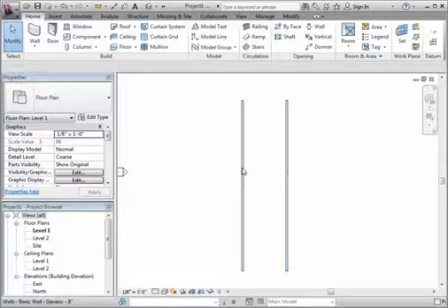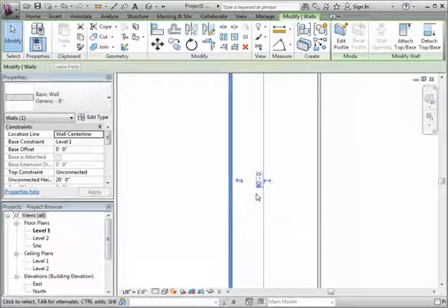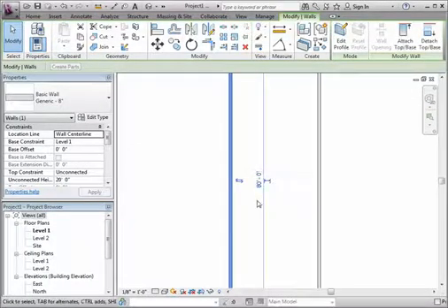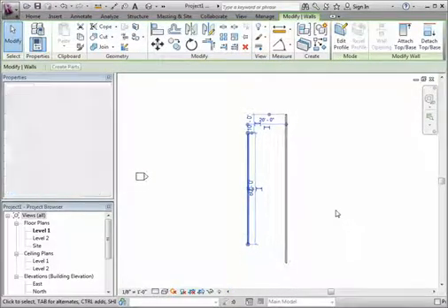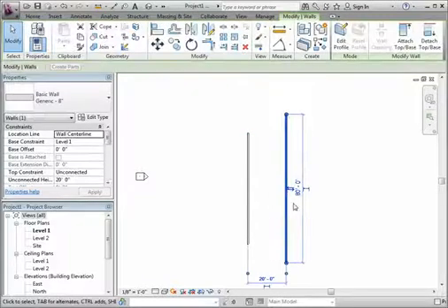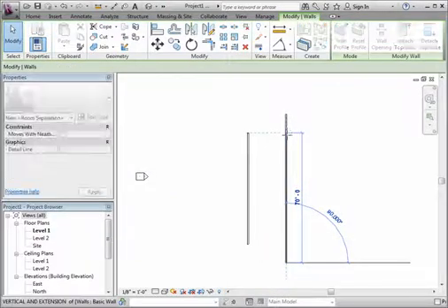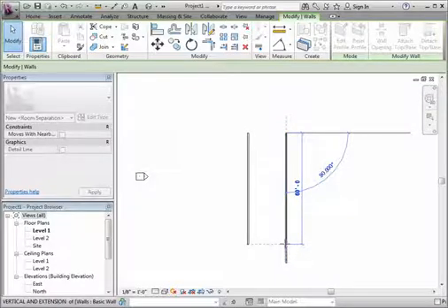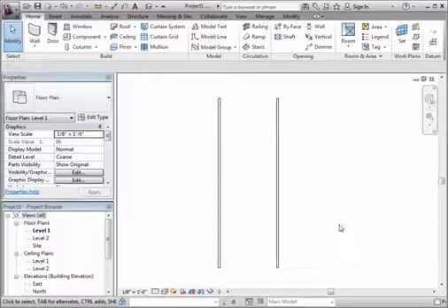So if I want to change them, I'm going to select one of these walls. And there's a couple ways I could change the length. You can see that this 80 feet here is also, again, in blue. If I click in that and type 60, the length would change. I could also drag, you have these grips on the ends. I could also drag the grips down. And you'll notice that it actually snaps to the ends. So that works pretty well.